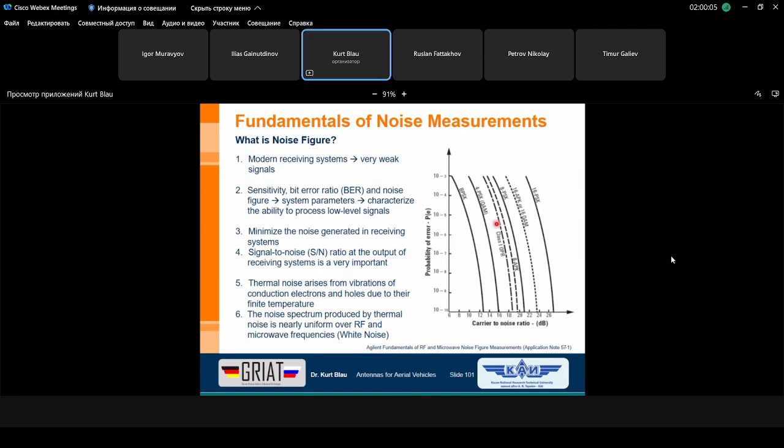So here you can see a very primitive example of modern radio. We have here different modulation schemes for the incoming signals. And this is a BPSK. It's only phase shift modulation, switching between plus and minus 90 degrees, for instance. It's only two states. Here we have four states. It's named QAM.